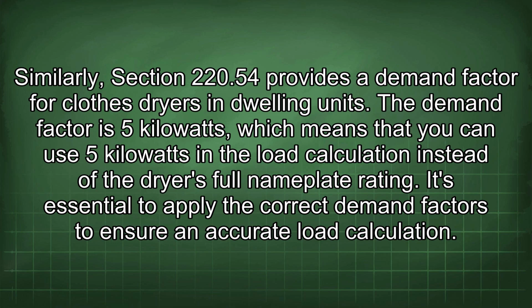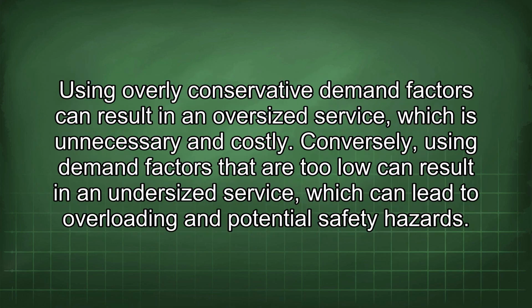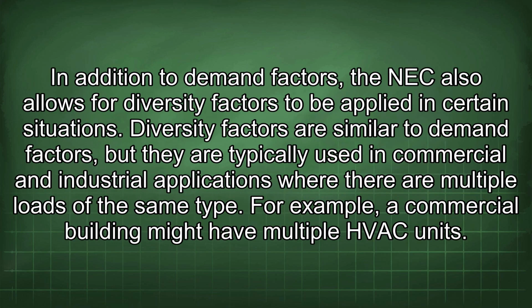It's essential to apply the correct demand factors to ensure an accurate load calculation. Using overly conservative demand factors can result in an oversized service, which is unnecessary and costly. Conversely, using demand factors that are too low can result in an undersized service, which can lead to overloading and potential safety hazards. In addition to demand factors, the NEC also allows for diversity factors to be applied in certain situations. Diversity factors are similar to demand factors, but they are typically used in commercial and industrial applications where there are multiple loads of the same type.